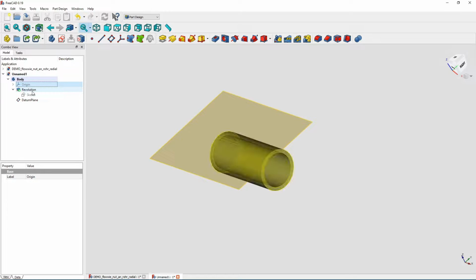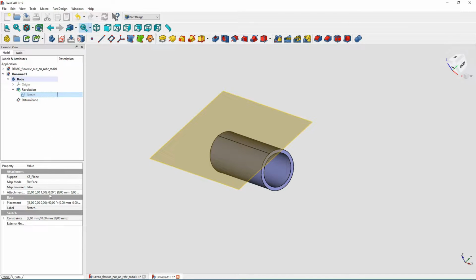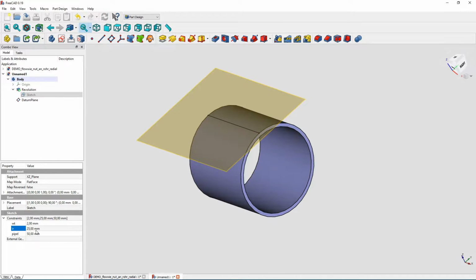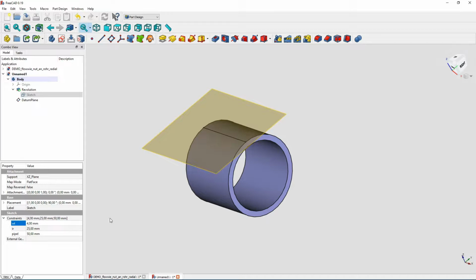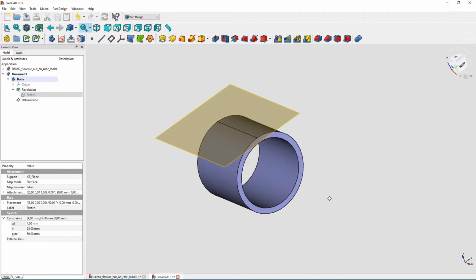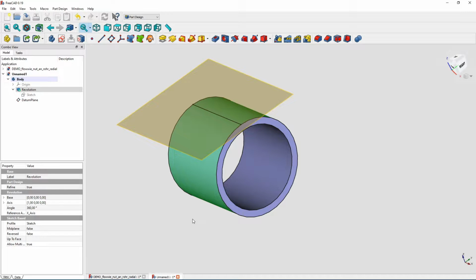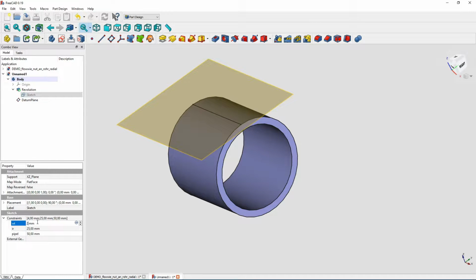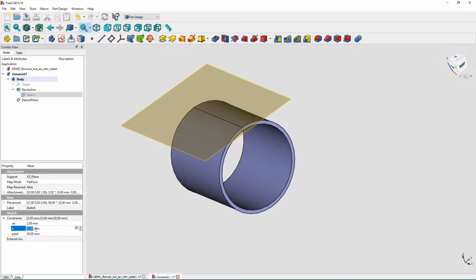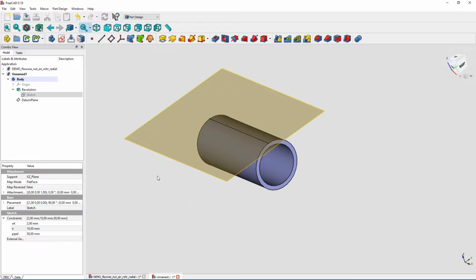path some mistakes. And so I will check this one and go for the constraints in my sketch and change the inner radius to 15 millimeter, for example, or 25 millimeters. And as you can see, the plane will always follow. So that's correct. I have a plane that's not glued on a surface like this one here, but is always following the outer radius of my pipe. That's exactly what I was planning to do. So I can change it back to the original values here, 2 and 10 millimeters, and then I can continue.